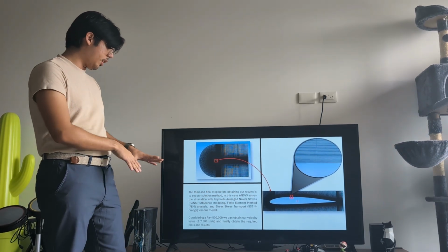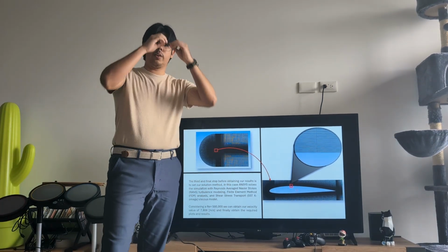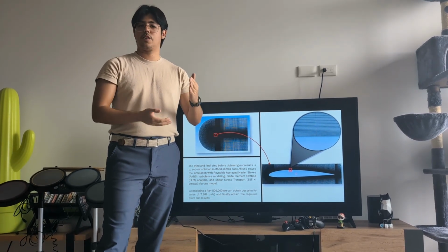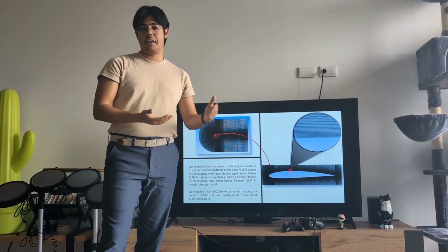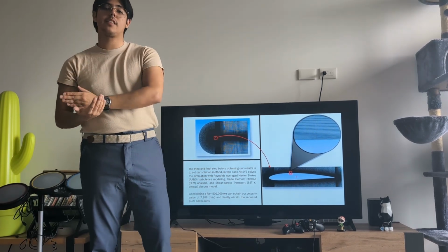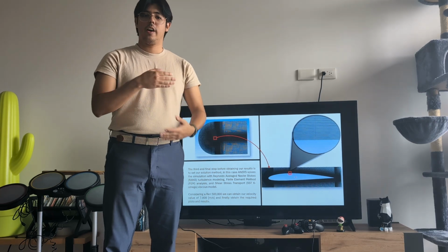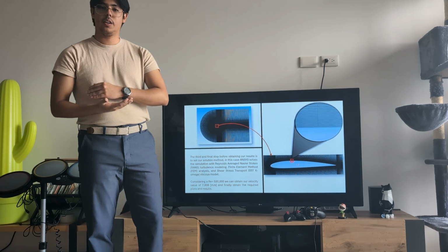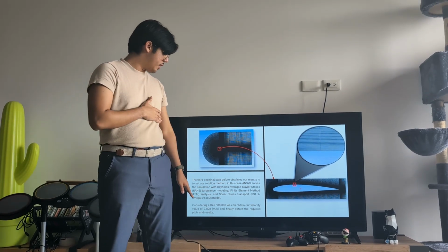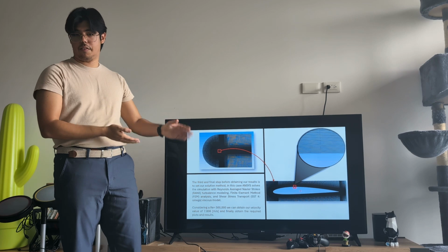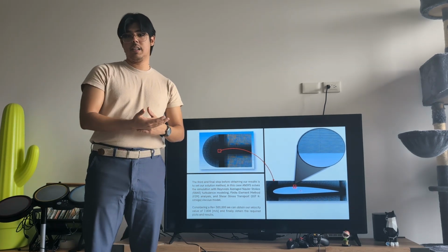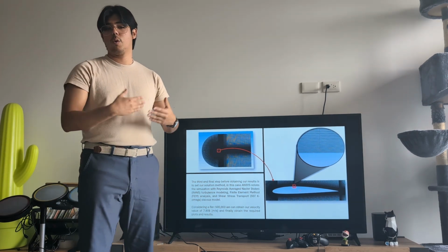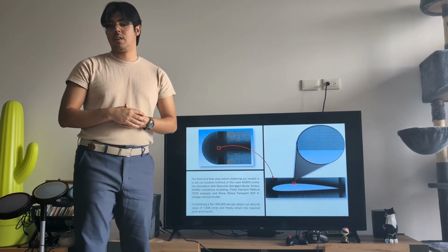Now, delving into our solution method, ANSYS Fluent solves the project with RANS, which is Reynolds Averaged Navier-Stokes, then FEM, which is finite element method analysis, and finally I chose a viscous model, which was the SST k-omega, which is shear stress transport. Now the parameters themselves, I chose a Reynolds number of 500,000, and this led me to my velocity of 7.828 meters per second, which is very common in low speed wind tunnels.